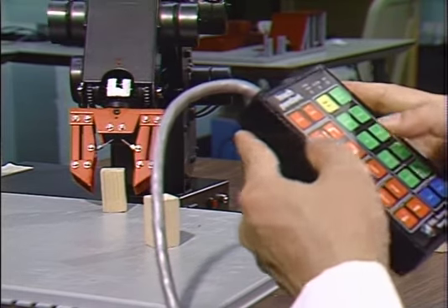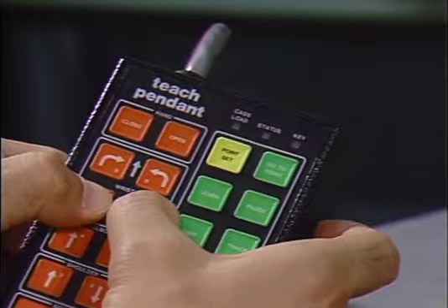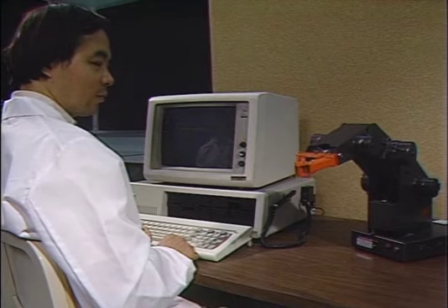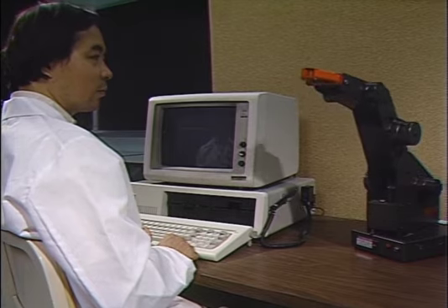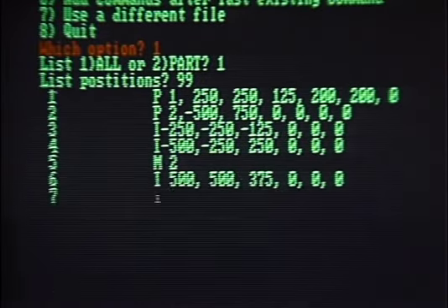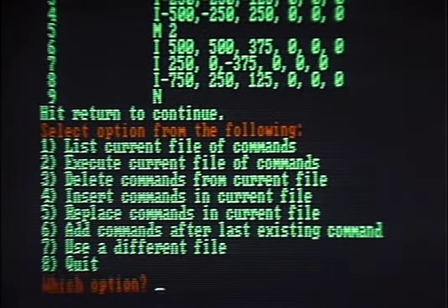In the lab, articulated robots driven by stepper motors are programmed and controlled with a teach pendant or from a host computer through a communication link. Each robot has an onboard microprocessor that interprets the incoming commands and translates them into pulses to the stepper motors that control the various joints. The use of a host computer allows offline programming, program verification, editing and simulation, as well as maintaining a database of programs on magnetic media.